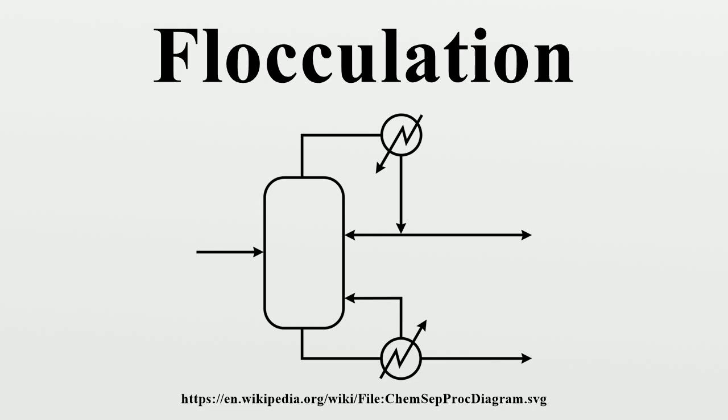Term definition. According to the IUPAC definition, flocculation is a process of contact and adhesion whereby the particles of a dispersion form larger size clusters. Flocculation is synonymous with agglomeration and coagulation, coalescence. Basically, coagulation is a process of addition of coagulant to destabilize a stabilized charged particle. Meanwhile, flocculation is a mixing technique that promotes agglomeration and makes particles settle down.